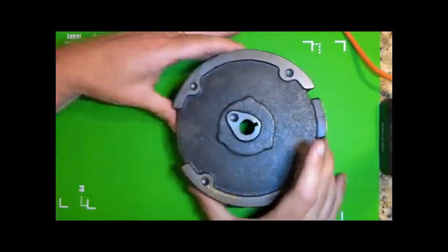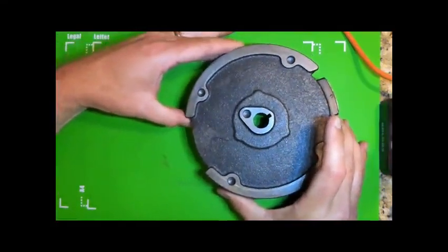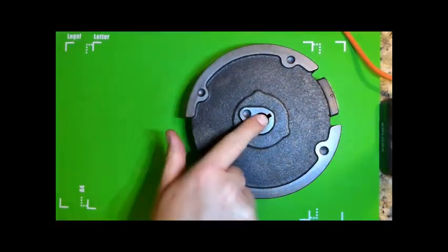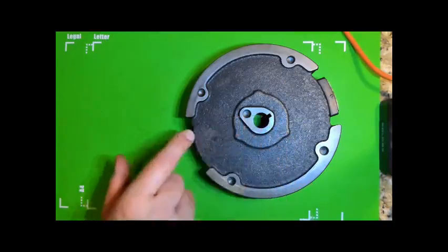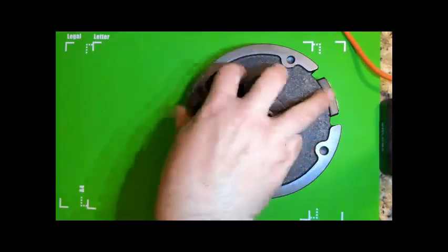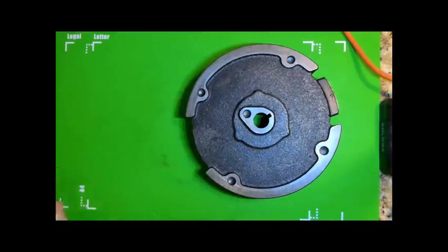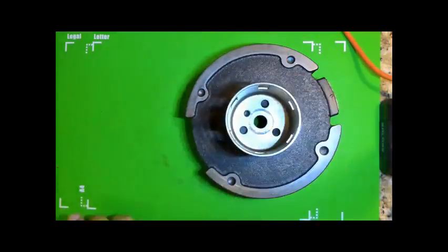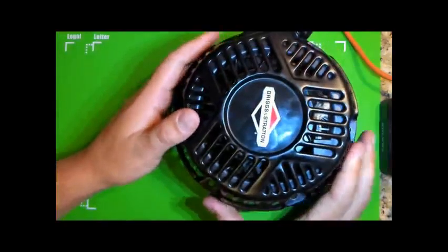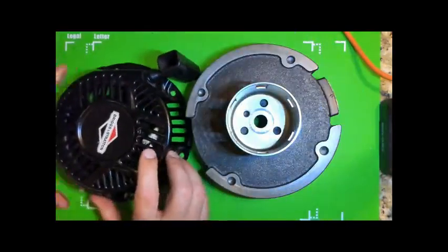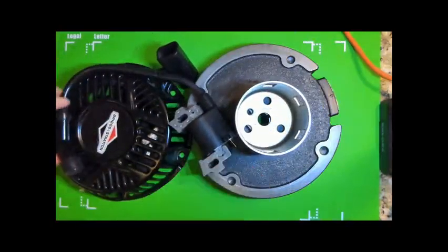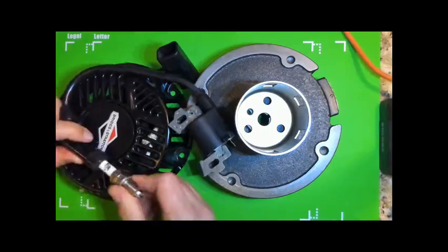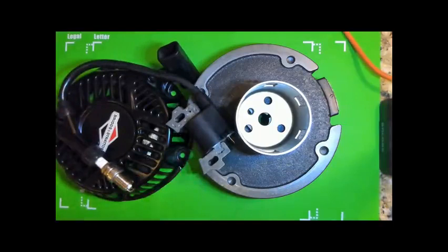So again, some of the main components that we're talking about with the electrical and ignition system is going to be, I'll start kind of small, the flywheel key, which is going to be a small piece of metal that's going to ride here in this notch in the flywheel, and also a corresponding notch in the crankshaft itself. The flywheel magnet, the flywheel cup, and I'll take it out to the actual recoil starter that we have to pull. We'll have our armature, and finally our spark plug. That's going to complete pretty much most of the ignition system.